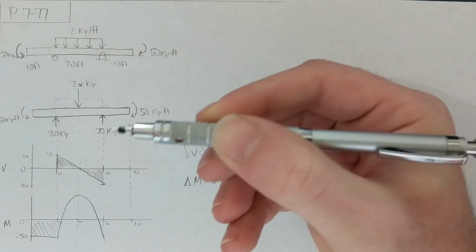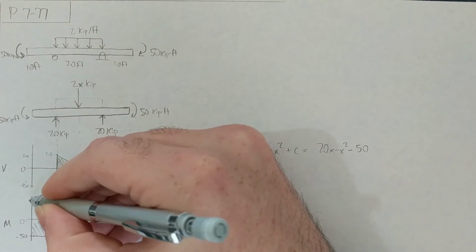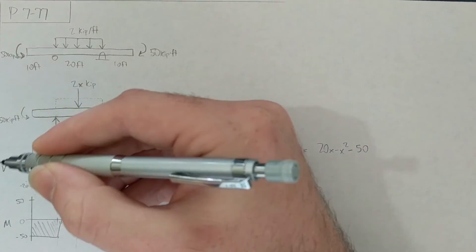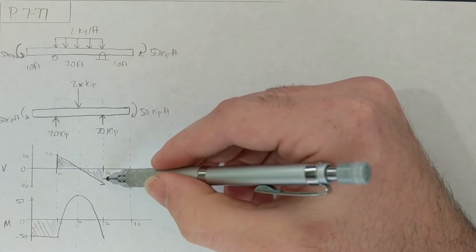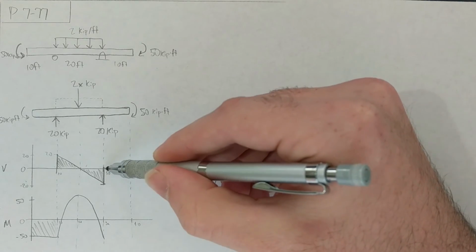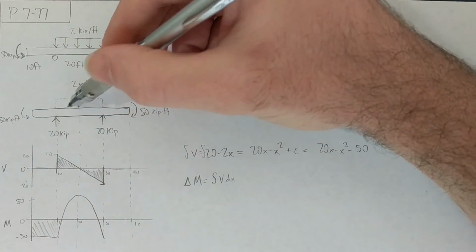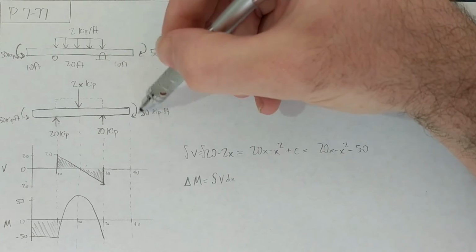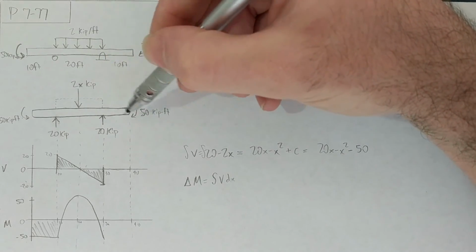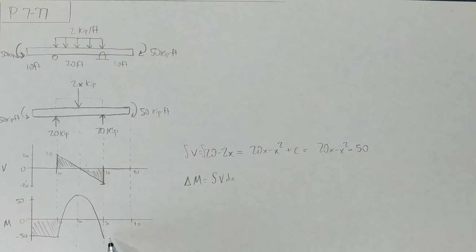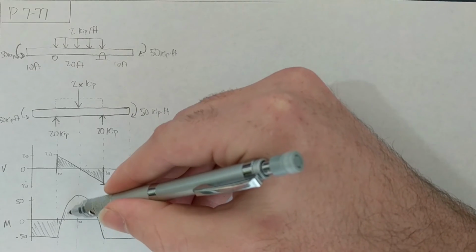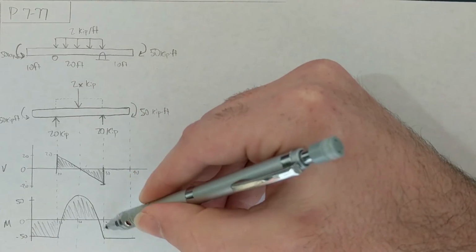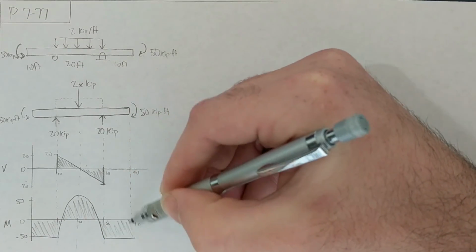Where this top bit ends up at plus 50. All right, and then on the other side, again, we have no shear, because these guys have all taken care of each other, and then this is just this hanging bar in pure bending of negative 50 again, because it's putting it concave down. And that gets us our whole thing.